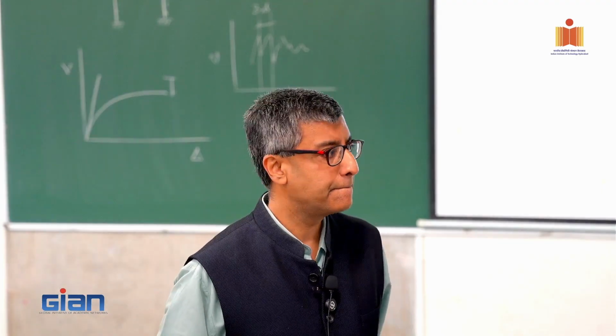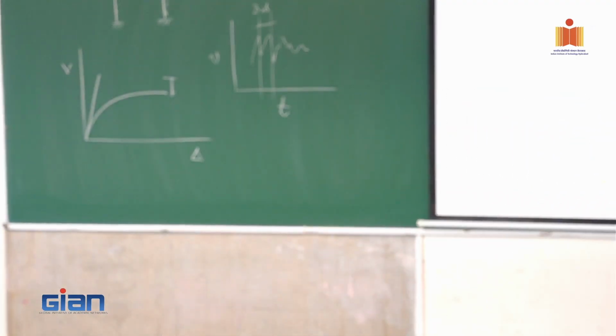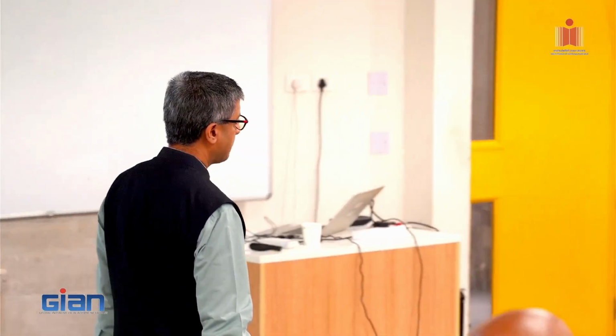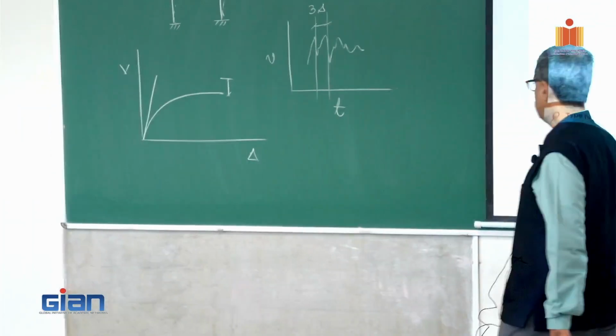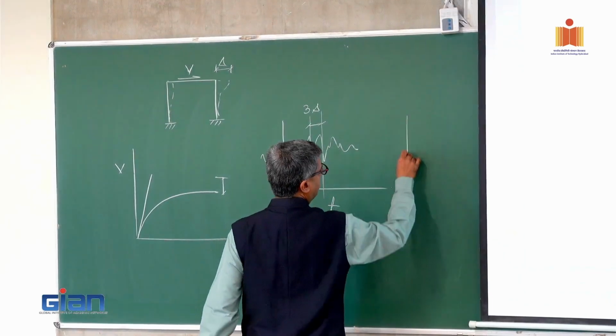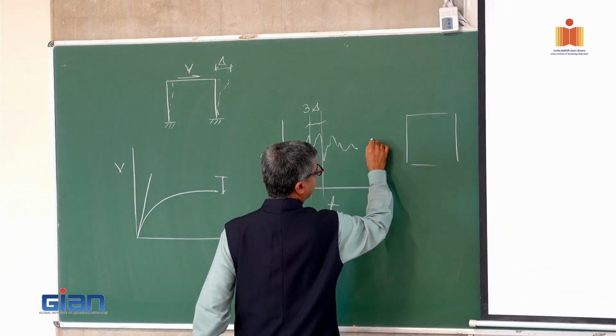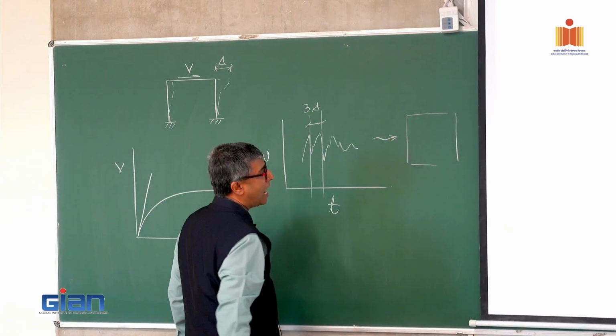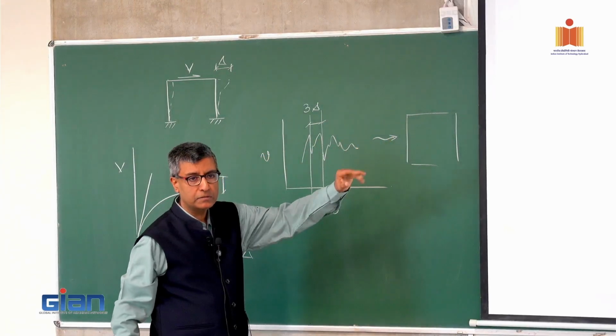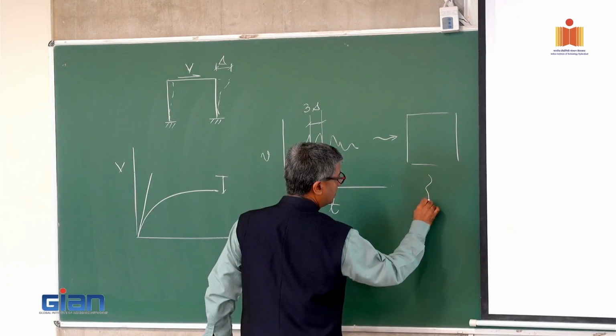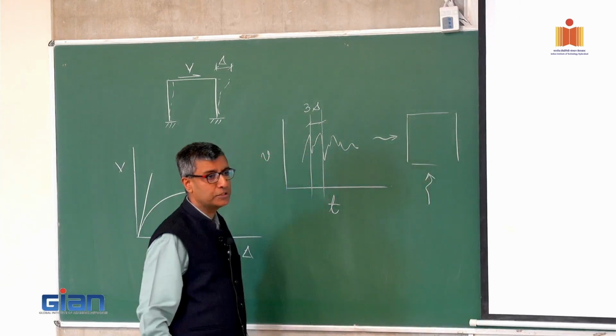So wind load calculations. Which one will be more critical? Wind loads acting exactly perpendicular to a side, or quartering loads acting at 45 degrees to a side? No, see, the idea for both wind and earthquake is that if I have a building like this, I will do one analysis in this direction, and I will do analysis in this direction.